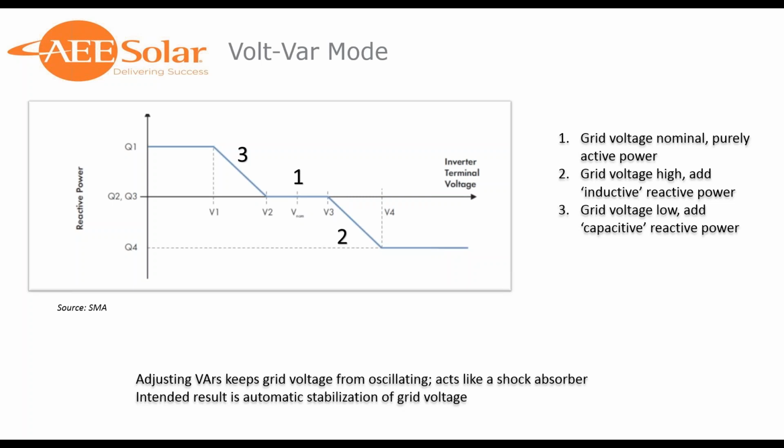It builds on the premise that an inverter is essentially a programmable power supply. The inverter is going to qualify a grid, and then it's going to mimic that grid as close as possible given its programming. It's going to follow that grid in terms of frequency and in terms of voltage. And while it's going to increase its voltage 1 or 2 volts to be able to provide a potential power flow out to the grid, it's going to mimic that as closely as possible.